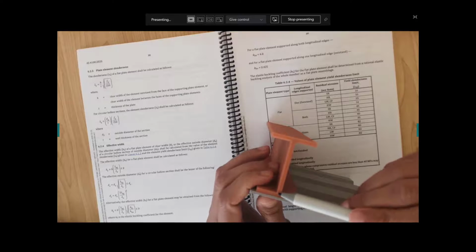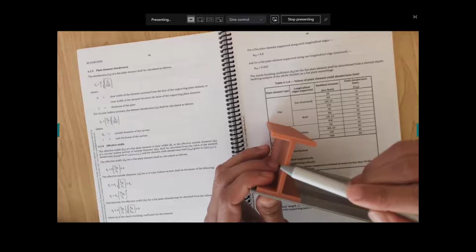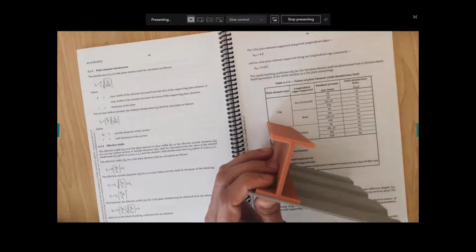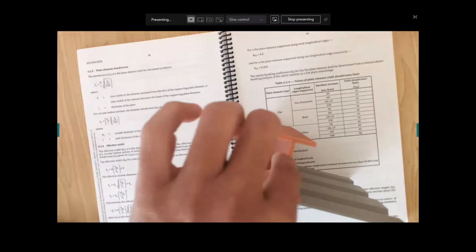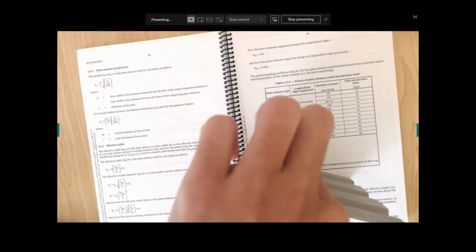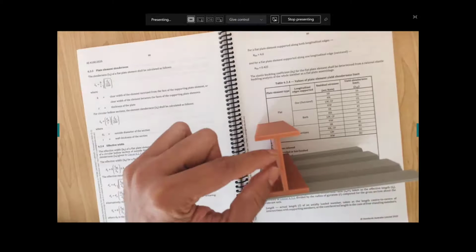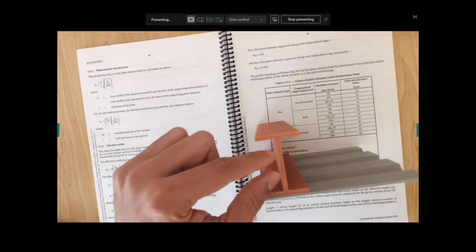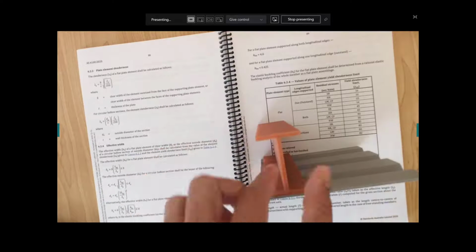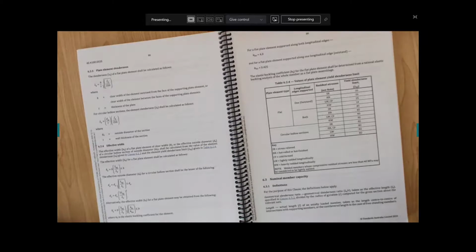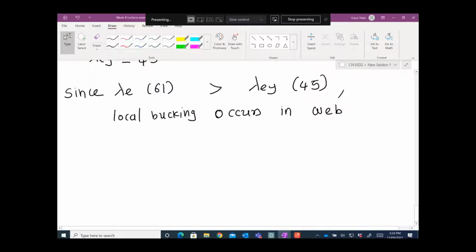This middle portion will be a straight line, and then it will come out, and then it will go straight again. So the standards will tell us how much of your material can be removed, because you can't use these materials. They will not carry the axial load. So this web is not fully effective. It has buckled, right? So in that case, the standards will tell us. Now how do the standards tell us? You can calculate BE, which is the effective width, and that BE is given here.